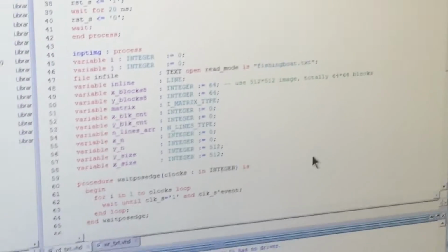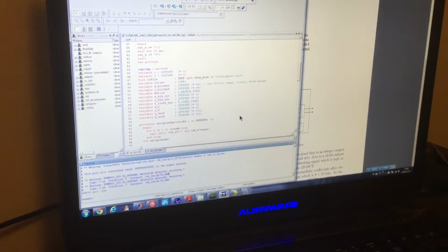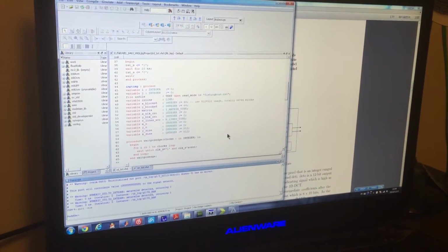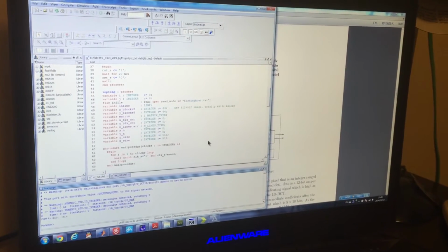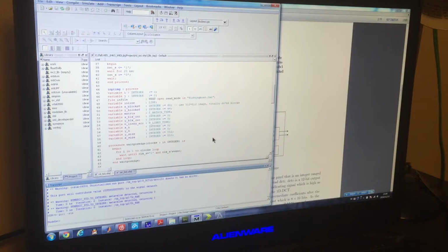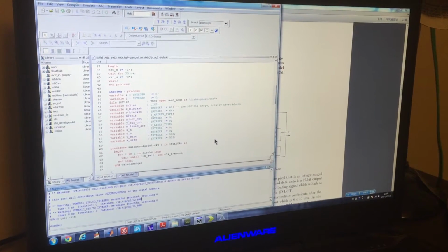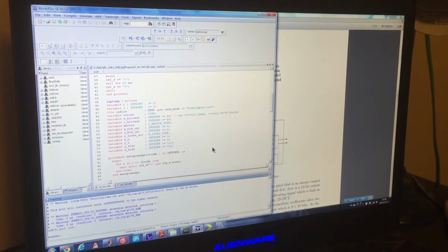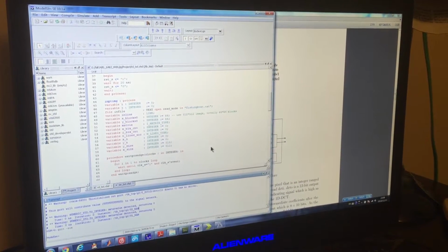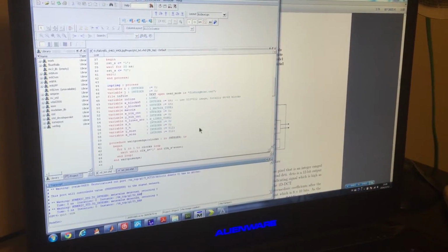And we have a slightly different test bench from what we have learned in class. It is because the DCT coefficient we get from MATLAB has decimals, and the output of our project are only integers. So there would be errors anyway. So in that case, we choose to store the values we got into a TXT file, and then we use MATLAB to measure the performance of our design. So here's how it works.